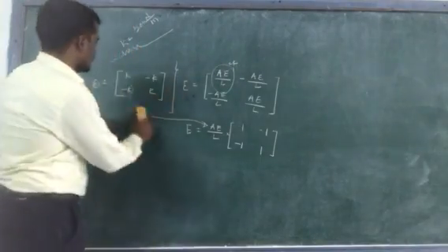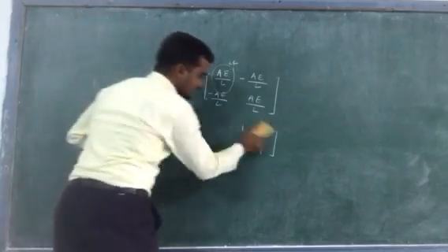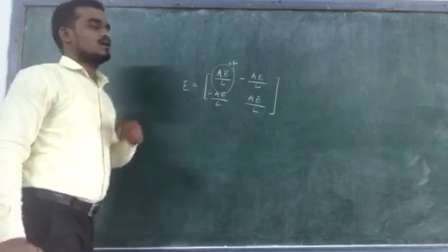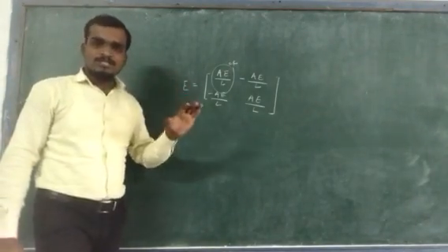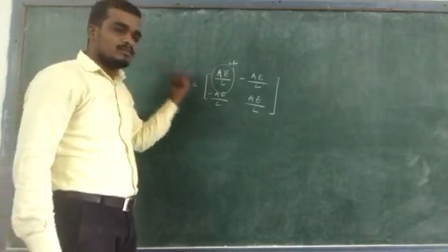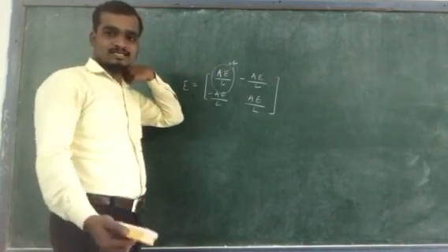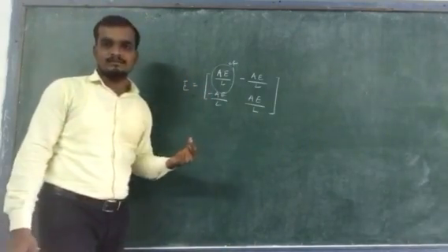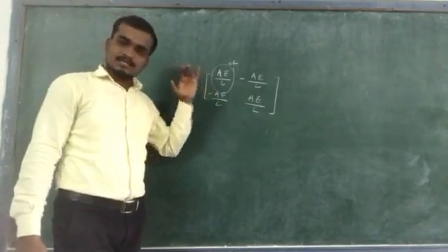By using this elemental stiffness matrix, the procedure is the same to find the stresses, reactions or displacements in the rod element. So what is the procedure? First, you need to find the elemental stiffness matrix for the bar or rod element. Next, assemble the elemental stiffness matrices globally, meaning you need to construct the global stiffness matrix. This is the second step.